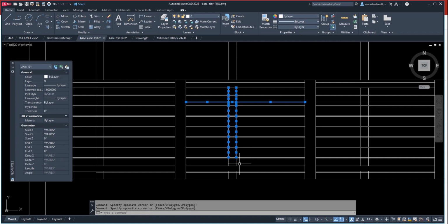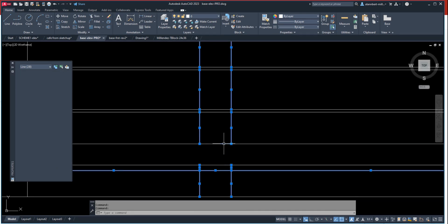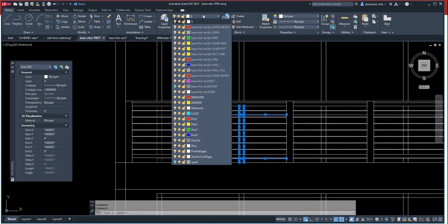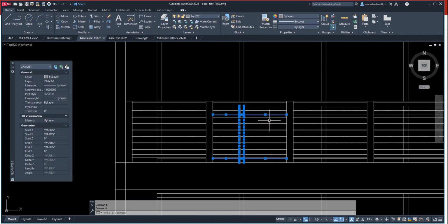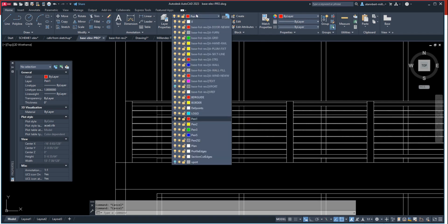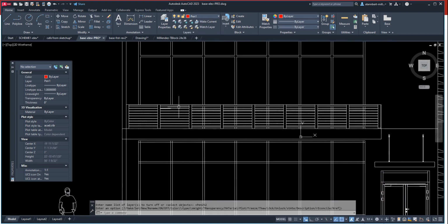So you're not drawing them anymore, but it still requires some work. I'm just pressing shift and unselecting. And this one too. Yeah, there you go. And then layer 252. Okay. So later on, we can turn off layer 252 and we'll just see these lines like this, which is much cleaner, right?